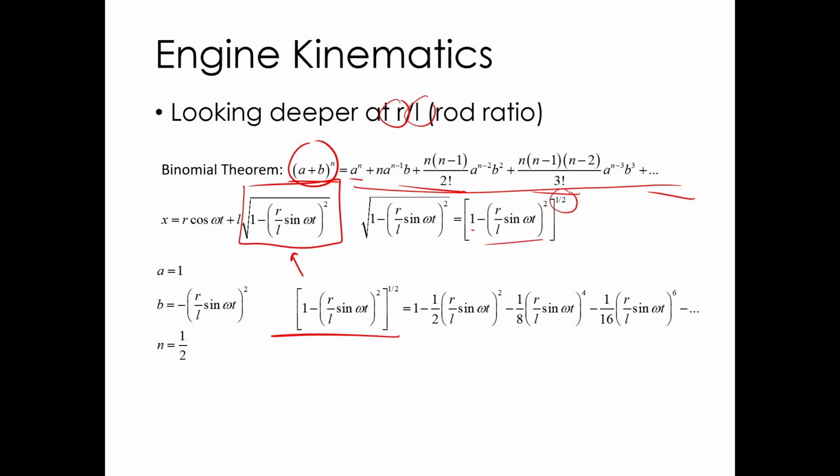When you start talking about factor of safety, you put a factor of safety on some systems of 2, 3, 4. It might be higher for some systems. For race cars, it might be closer to 1. But the reason you put a factor of safety on is because there are a lot of unknowns in systems. There's always variability in engineering systems. So for a lot of the things we do, we don't need an insane amount of precision. So maybe somewhere out here, these terms are just not that important.